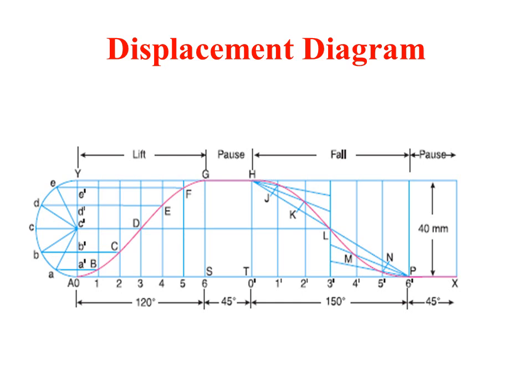After that, as mentioned clearly in the problem, the lift or outstroke has simple harmonic motion. Whenever there is a problem with simple harmonic motion, we have to draw a semicircle as shown here, and this semicircle will be divided into an equal number of even parts, same as that of lift or fall, that is 6.